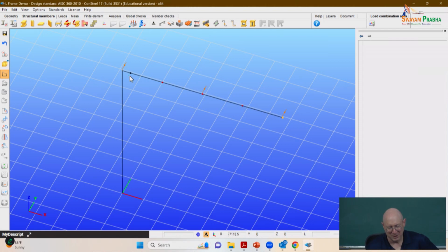Now in metal building design, many metal building manufacturers will design their frame where every purlin and girt location is assumed to be braced, both flanges, with flange diagonals from girts and purlins to the inside flange. They design the frame that way, and then they have a bracing reduction stage where they come back and ask what flange diagonals can we pull out where it doesn't change the design.